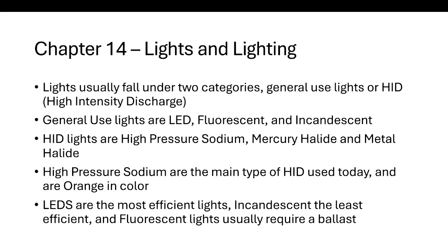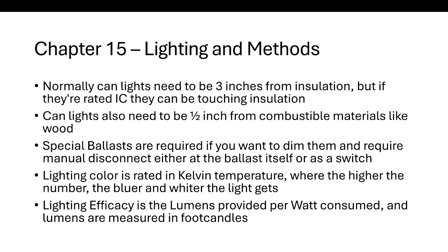LEDs are the most efficient lights, incandescent are the least efficient, and fluorescent lights usually require a ballast. Okay. Normally, can lights need to be 3 inches from insulation, but if they're rated IC, they can be touching the insulation. IC meaning in contact, essentially.